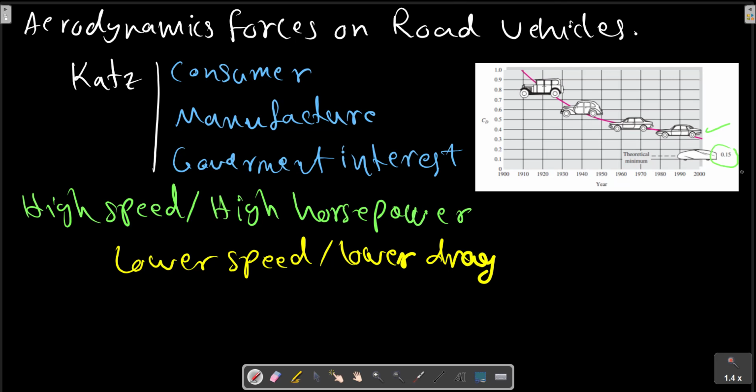Note that basing drag coefficient on the frontal area is awkward, since one would need an accurate drawing of the automobile to estimate its frontal area. For this reason, some technical articles simply report the raw drag in newtons or pound force, or the product of this relation. Many companies and laboratories have automotive wind tunnels, some full scale, with moving floors to approximate actual kinematic similarity.